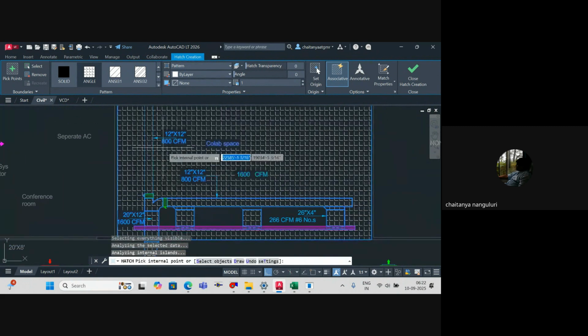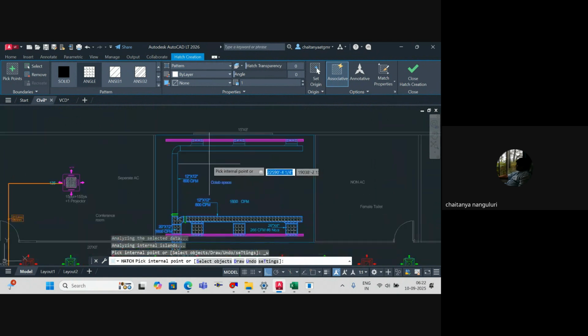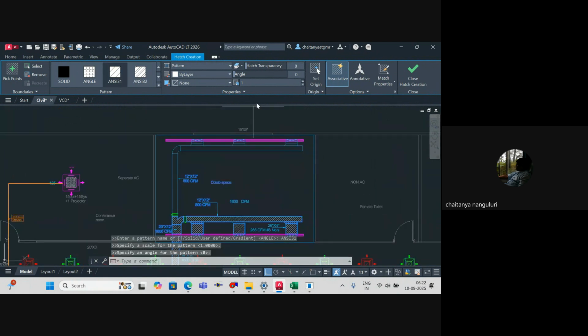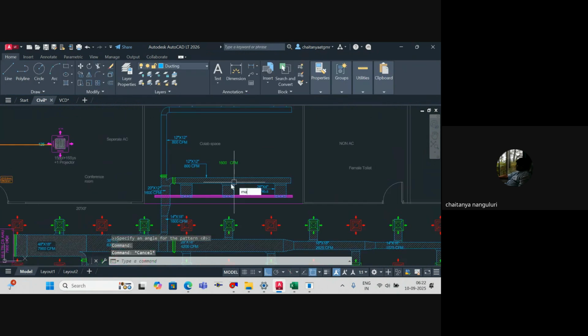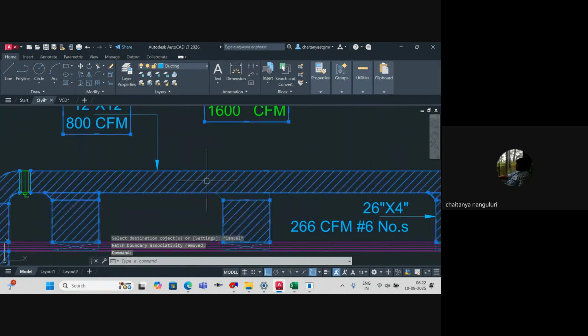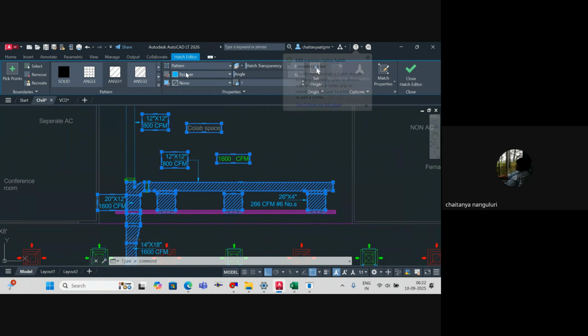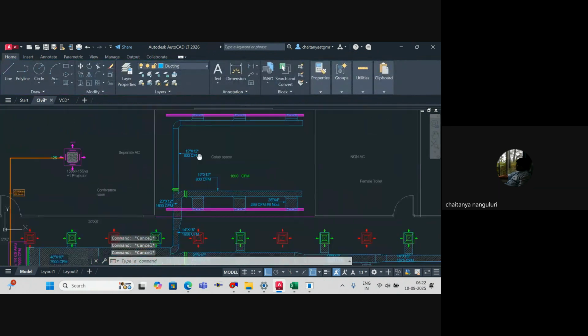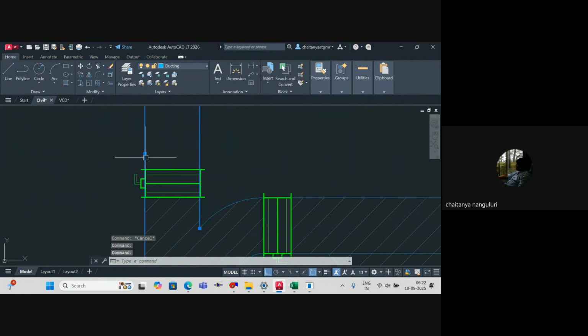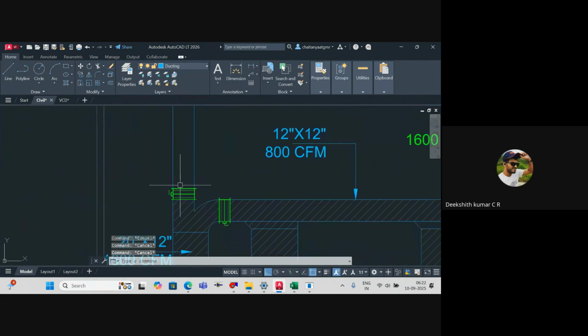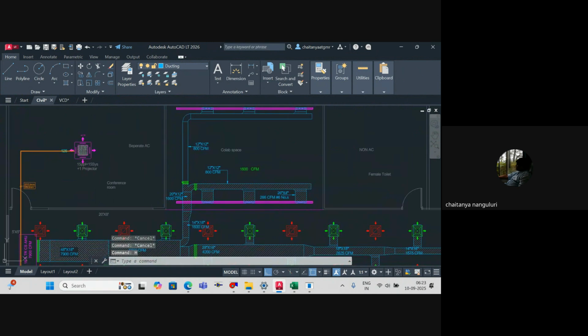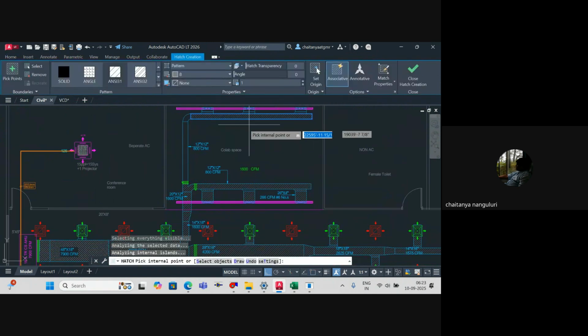In the olden days we used to do insulation only at the tail end. But now we have changed that procedure. The reason is simple: if you go only for the tail end, the temperature at the final grills will be off, and the temperature at the final end will be very hot. Understood? That's the reason we have stopped. We are doing entire thermal insulation nowadays.